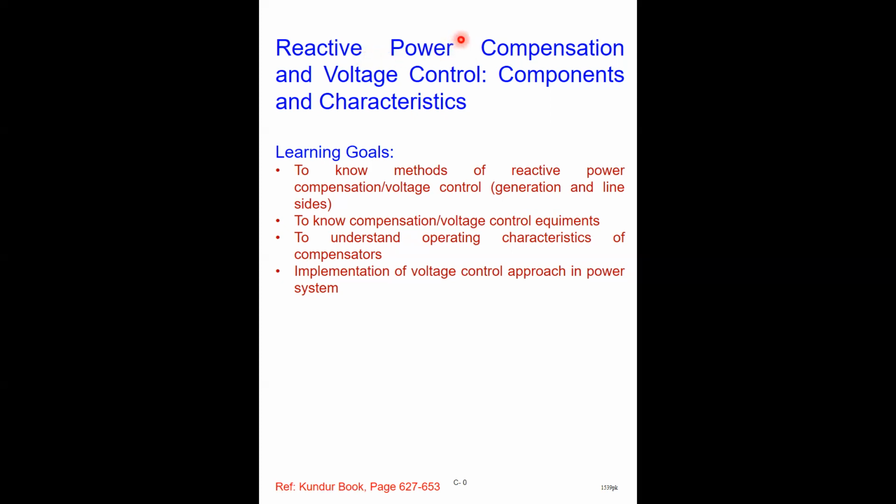So the reactive power generation and the consumption in the system will depend upon the situation. And thus the voltage control is a little bit more tricky as compared to the active power and frequency control, because there are several components involved towards reactive power, either as a source or a load consumption.